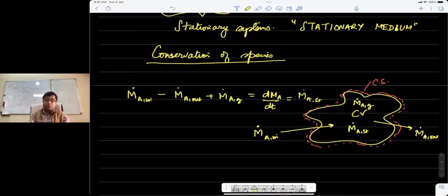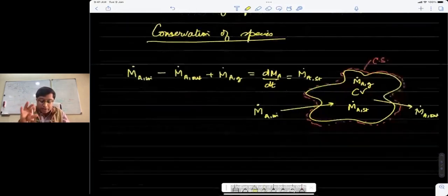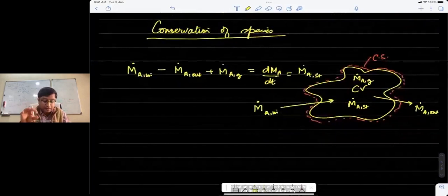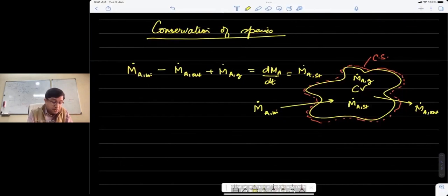Take an infinitesimal control volume, write the fluxes on all the faces of the control volume, include all terms in this manner. For an infinitesimal volume, you also take an infinitesimal element size, so the volume size, which is delta x, delta y, delta z, so and so forth. I'm not going to go into the derivation there, except that you can finally obtain a simplified form of conservation equation, a partial differential equation for conserving this species A, under certain approximations or under certain assumptions.